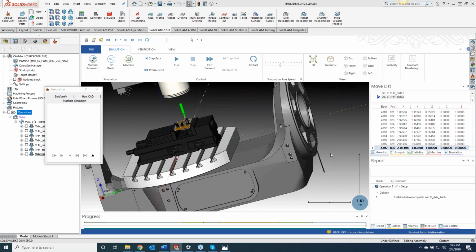Any questions with thread milling? I've got one. Oh boy. Ronnie set the bar here, so I have to do my best to try to one-up him. But within thread milling, we've seen a couple different strategies here, and you've shown a strategy that has taken the thread in multiple Z depths, and then you've also shown strategies that are a continuous helix. Is part of a stump the instructor question. What's the differentiating factor between whether or not we're going to take this in multiple Z depths or as one continuous helix? All based off of the number of teeth.